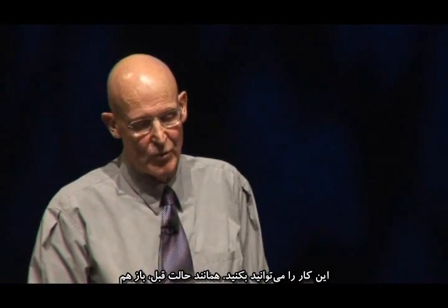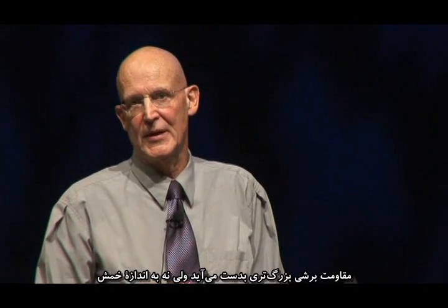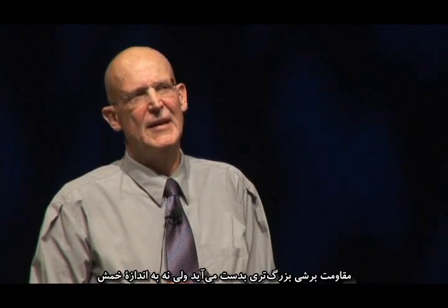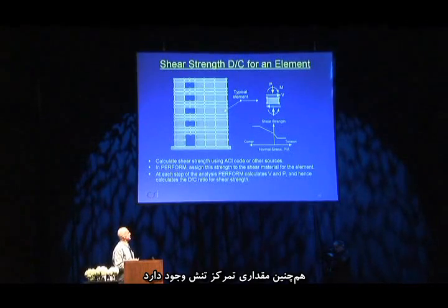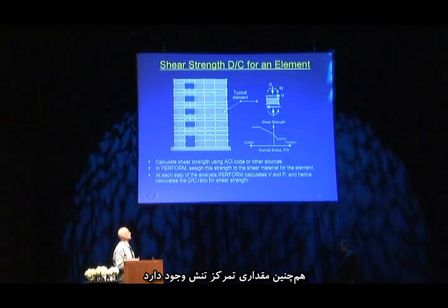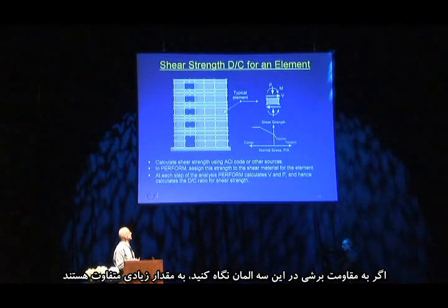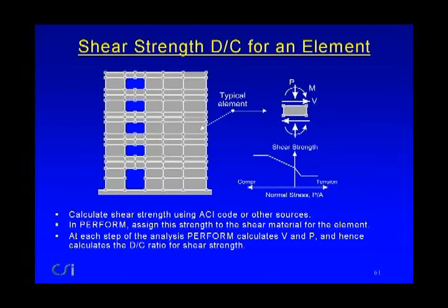You can do this if you wish. The problem is you run into the same problem that you had previously: as you refine the mesh, you may start getting larger and larger shear strains. Not as much as bending, but there does tend to be some shear strain concentration. If you look at the shear strains in these three elements, they're likely to be substantially different. And basing the decision on the worst of these three elements might not be such a good idea.